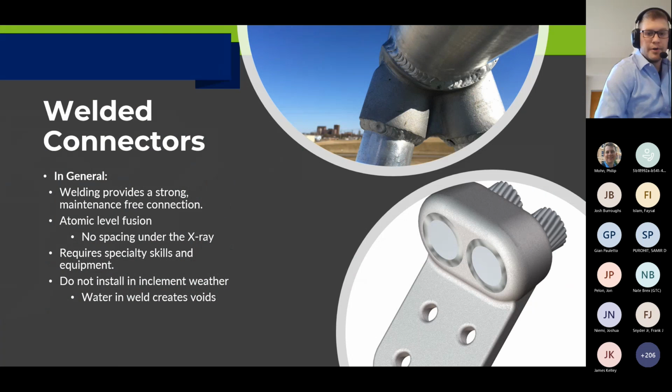So starting off with welded type connectors, I have two pictures here. The first one at the bottom is showing you cable to flat, two conductors coming in where they weld the actual conductors to this connector member. And then you'd land your 4-hole pad on your switch pads, or if it's jumping off of a bus run or a transformer and breaker.